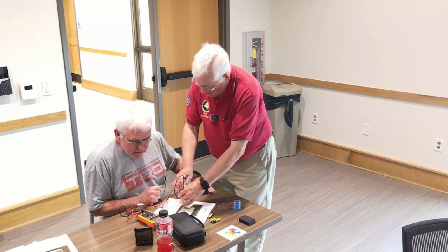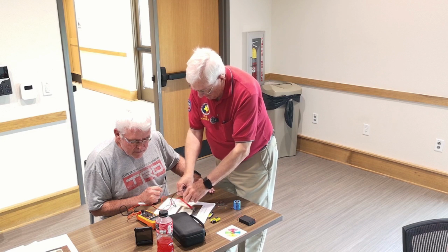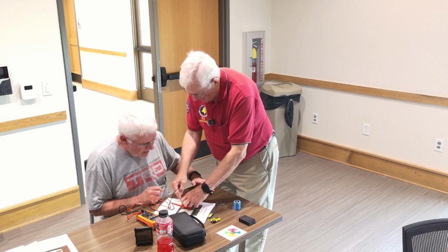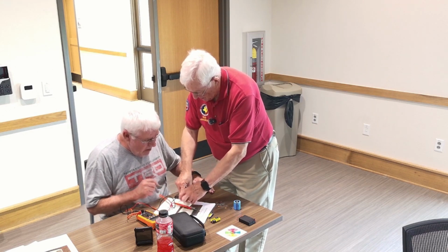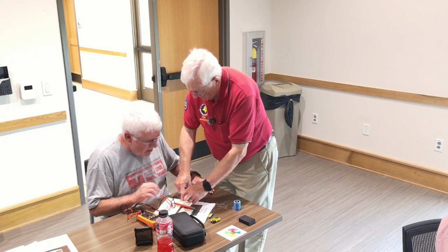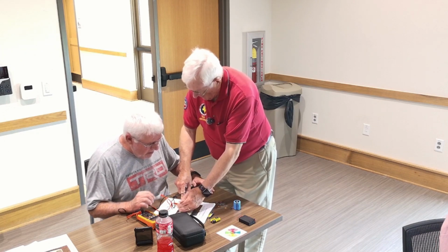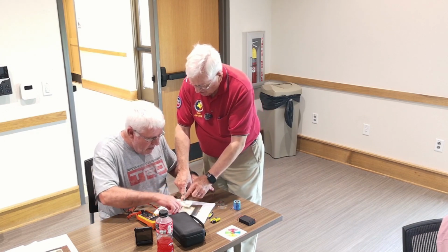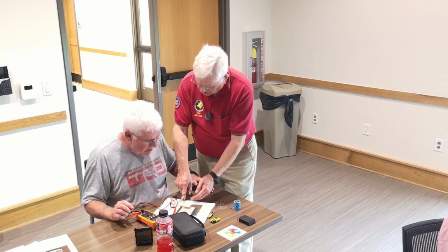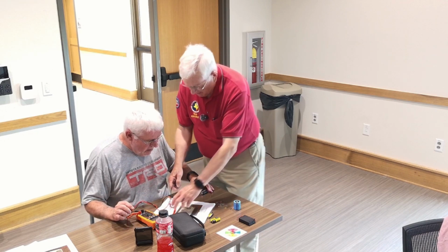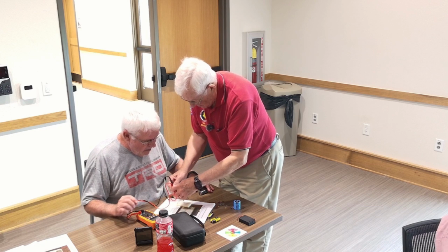Now, if we took this and suddenly moved it over to here, where the resistor is across these two leads, then this will discharge much more rapidly. But the idea is this resistor doesn't let this charge up immediately. It charges up real slow as it goes up. So let's put it on there again and we'll watch it happen.